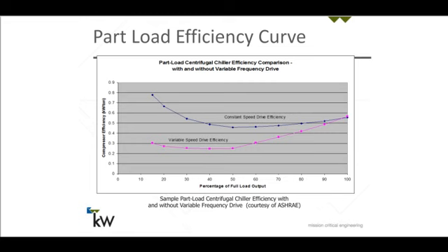But if you apply a variable speed drive, at 30%, 40%, 50%, 60%, it's a real sweet spot on many machines, and you can significantly improve chiller performance. You're under 0.3 kW per ton, and this is applied at conventional chilled water temperatures. You start applying the variable speed drives at elevated temperatures, your chiller efficiencies are even better.